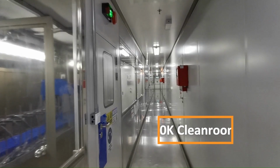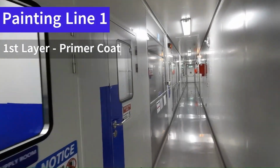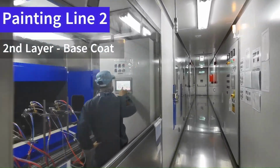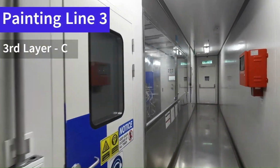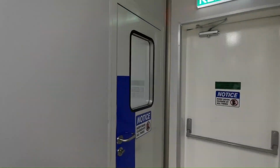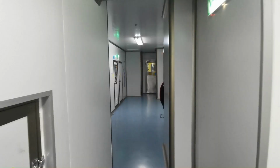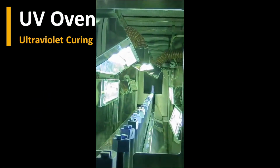Our painting has 3 lines connected together by a conveyor system. It was designed for the primer layer, base coat layer, and top coat layer. Each line has its own auto dedust system, spray booth, pump system, and oven. Line number 1 and number 2 have identical systems, while line 3 has 2 heating ovens for longer curing time. It's also equipped with a UV oven curing system, which is specialized for UV paint curing.